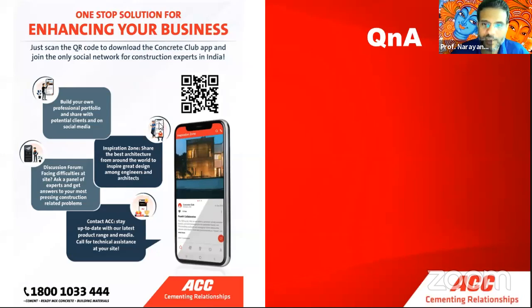What amount of calcium hydroxide in this concrete? Calcium hydroxide essentially is a function of how much cement has hydrated. And since my degree of hydration of cement is 0.25, 0.3 max, my calcium hydroxide content also is going to be very low. So the question is that if the calcium hydroxide is low, what will happen to durability? Corrosion guys, I know it's a corrosion question, and corrosion guys would love that question.